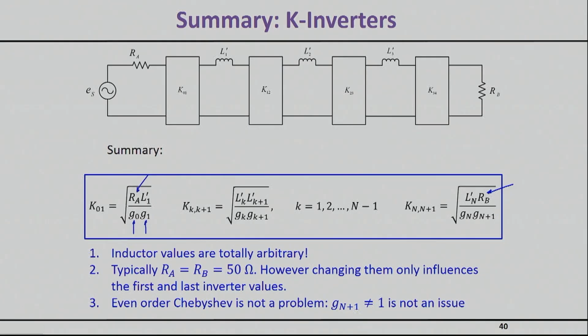As I mentioned before, one of the big advantages of this approach is that you can scale the filter very quickly just by changing the first and the last coupling sections if your impedances end up changing, which is again an amazing convenience.